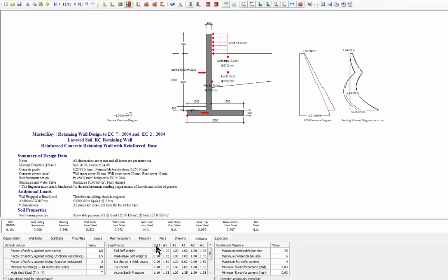So we're looking at our equilibrium and our A1 and A2 loads. And for your active, your tie forces, your surcharge, your base loads, and all the way down to nib passive and nib active, if you really want to try and make that nib give you great benefit. And then some simple limits on the reinforcement and our factors of safety against sliding and overturning.